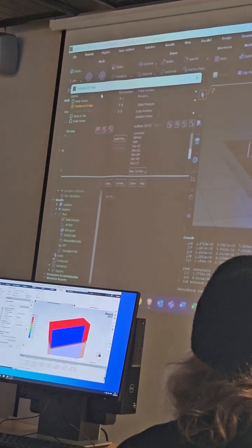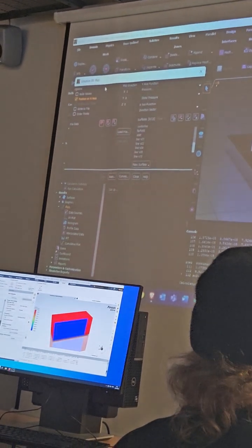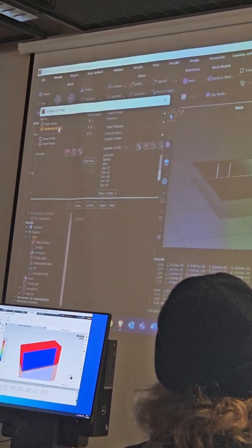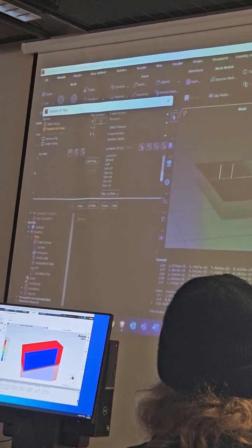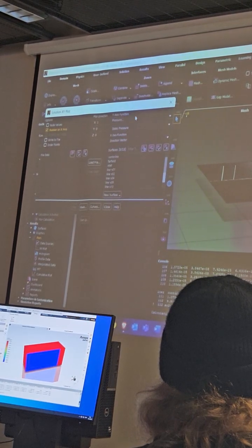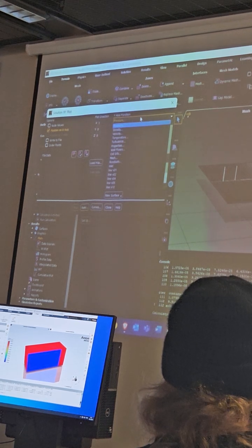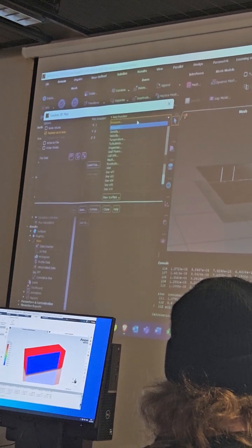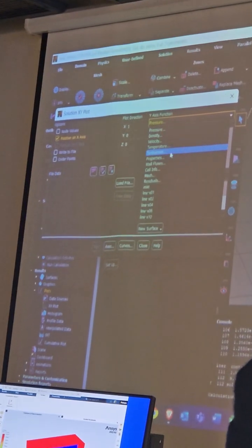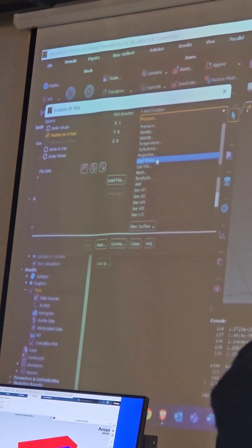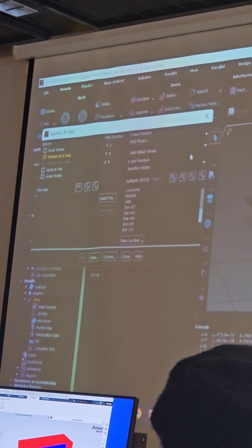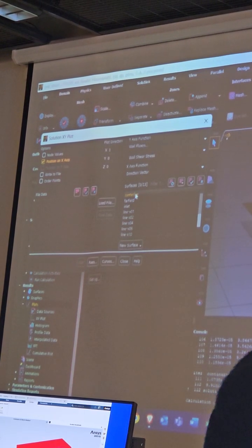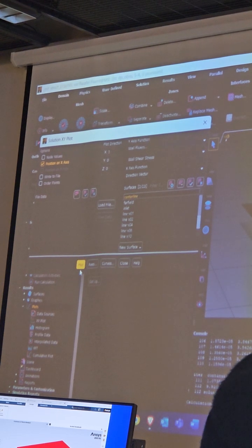So then we can start with the center line. For the center line, we can leave this position on x-axis, since the center line is along the x-axis. So plot direction x, that's correct. And in the y-axis function, we can plot the wall shear stress, because we need the wall shear stress along the plane. So we go to Wall Fluxes here, and the option is already there, so it's Wall Shear Stress. In Surfaces, we select center line, and we can plot.